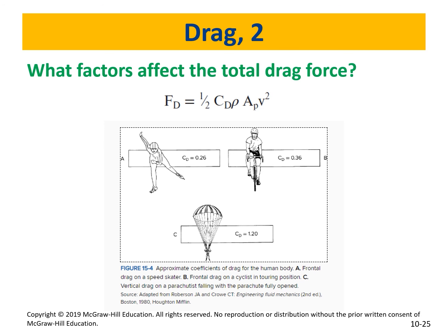Skater, right? Ice skater. Because of what they're wearing and how the body is actually moving, they have a CD of 0.26, the coefficient of drag. Now, if it's a biker, the coefficient of drag is larger because we have a larger area that the biker is actually covering. Now, a parachute is 1.2. So it's a geometrical quantity that dictates the value of that thing.